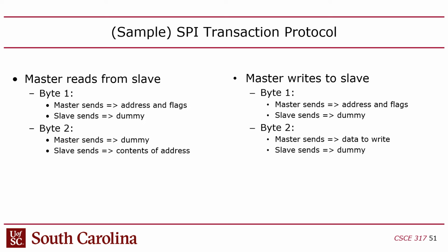And you might say, why? Because generally speaking, the peripherals are going to have more than one register that you can address, at least configure and data. A good example of this is when we originally designed this course, we were going to have you attach a little screen to the Arduino, and you would put images on the screen through SPI. So you literally would have to tell it what pixel you want to light up on the screen and what color you wanted to make it. So there are all these addresses on the peripheral, so you have to send an address to read or to write.